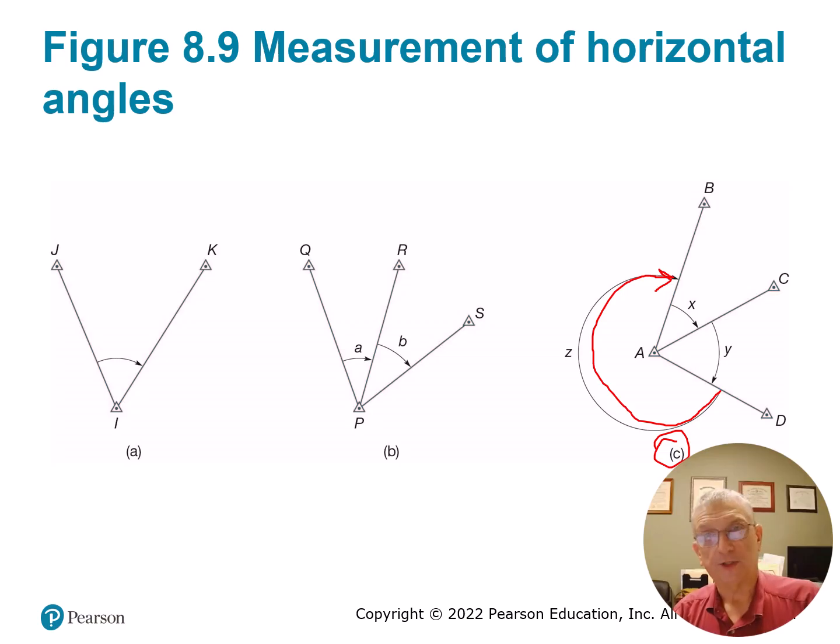Another weakness with the traditional double angle is if you have any kind of collimation error or any kind of centering error in your instrument, you're not compensating for it. You're just taking 2 redundant direct observations. If your instrument has any kind of error in it, which they all do, some of it fairly non-detectable, when you take a reversed scope, then you're accounting for that. So your average is probably pretty good.